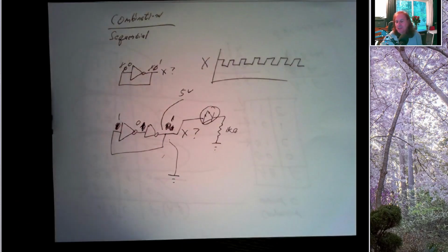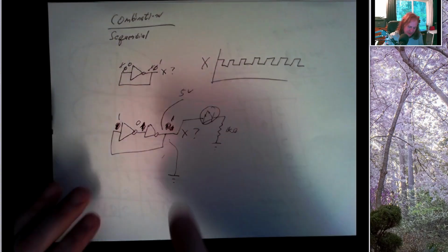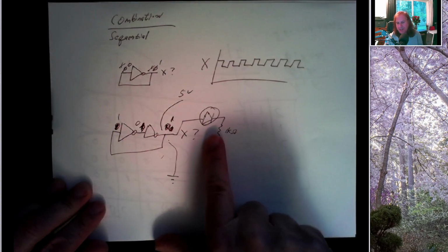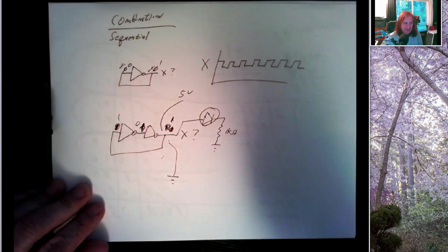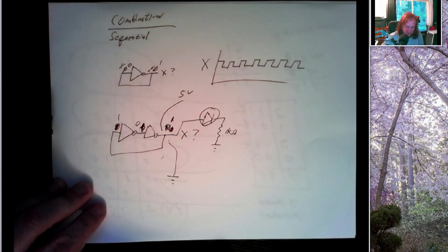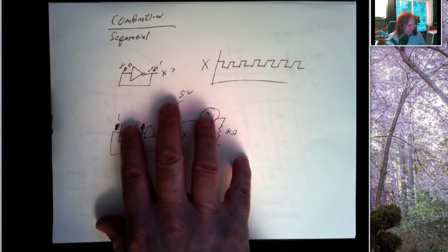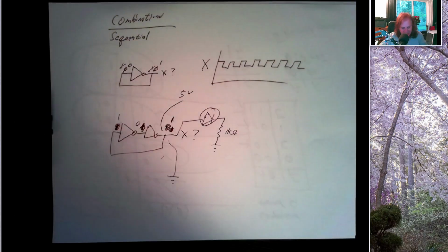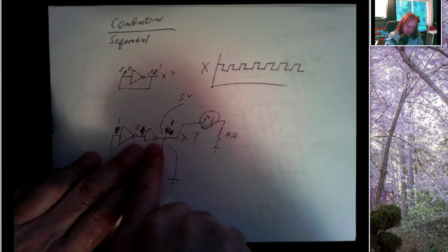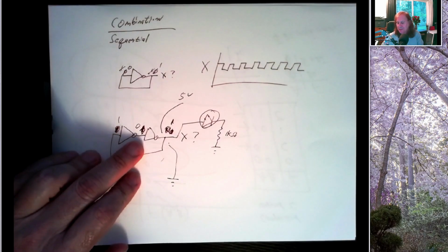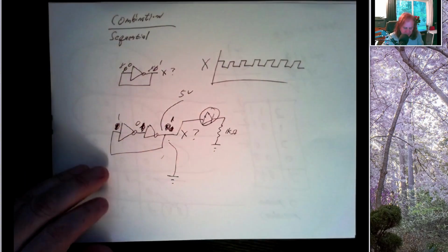So that's a memory circuit, right? It can remember the last event that happened to it. Was this point temporarily connected to 5 volts or ground? And it'll turn the LED on to say 5 volts, off to say ground. Okay, that's the basic building block of a memory, but it's not practical because, as I said, we don't actually want to take a circuit that's trying to generate a voltage level and connect a different voltage level to it, right? That creates a short circuit.